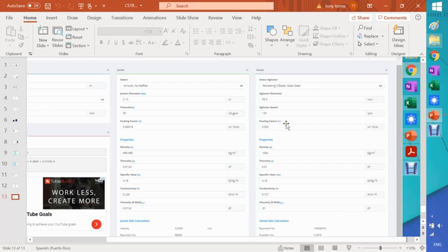0.0025, but I screwed up something here. Basically, the fouling factor that I'm using inside is for the glass lining, which is the thickness of the glass, about 0.002, divided by the conductivity of the glass, which is about 0.8.